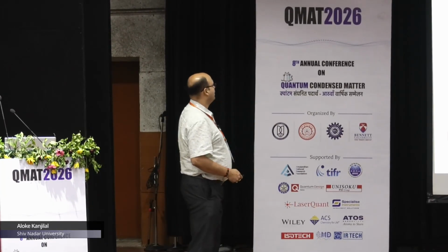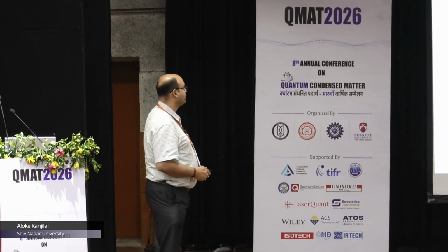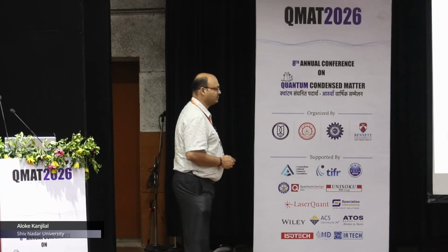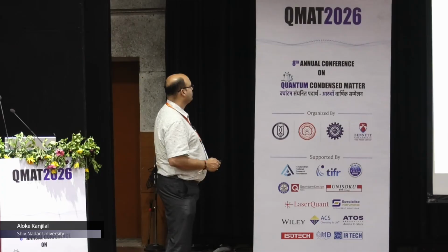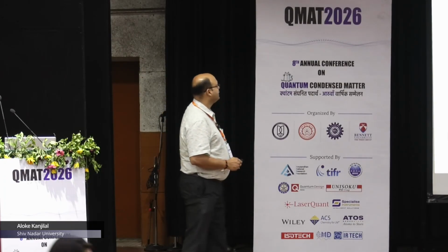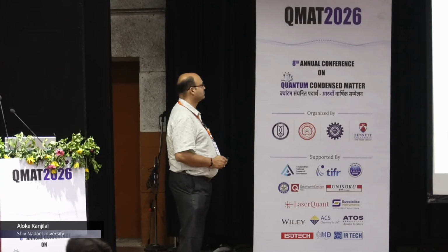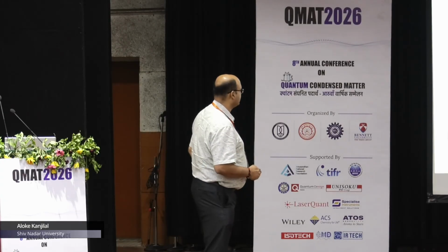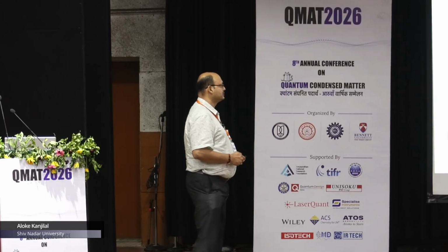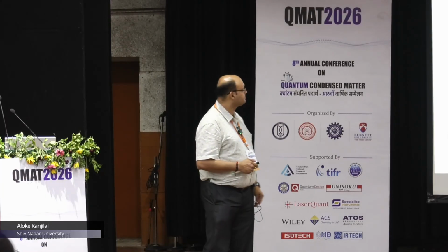Anyway, what I'm going to show is something interesting we recently published, working with a bilayer structure of hBN and hafnium oxide. Both are dielectric materials, one 2D and one 3D, so a 2D-3D combination. I am going to show the atomic filamentation, because of how this controls your quantum conductance quantization, that is, how the conducting path is forming. That is what I have to discuss in this topic.